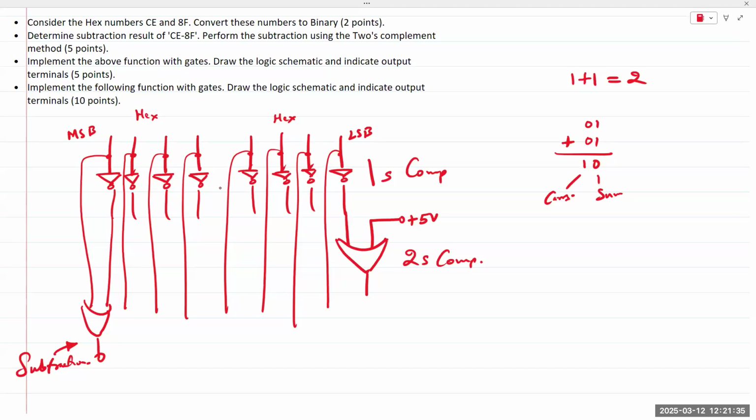But this problem was not something where I'm looking for students to get 100%. It's not fair because this is not something we do for E321. But as part of the larger question, I just wanted to see what students would do about it. So we'd have a circuit for a 1-bit circuit. You'd have it created with like 4 gates. We'd incorporate an XOR, or there are many ways to do that, but you'd have 2 outputs: a sum output and a carry output. It's known as a 1-bit adder circuit.